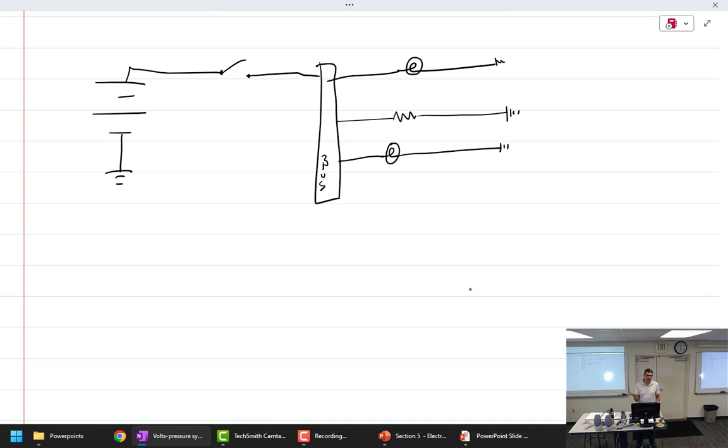In an aircraft, it'll run through solenoids and switches and go to a bus bar, which is a distribution bar, right? Mine is right under my knees, right behind me where all the circuit breakers are. And then from there, we'll have circuit breakers. That's a circuit breaker to another switch. This would actually be a solenoid right here. Anyway, it goes out to each component, and of course there are a lot of components. If I had to troubleshoot this, I would say, well, it goes from negative to positive, and I'd have to go from the negative.